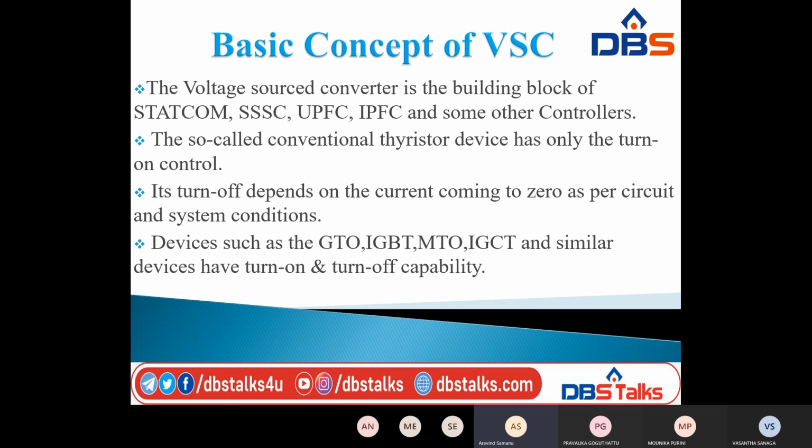In the voltage source converters we have the STATCOM, SSSC, UPFC, and IPFC. STATCOM is a shunt connected controller, SSSC is a series connected controller, and UPFC and IPFC are combined series and shunt controllers.